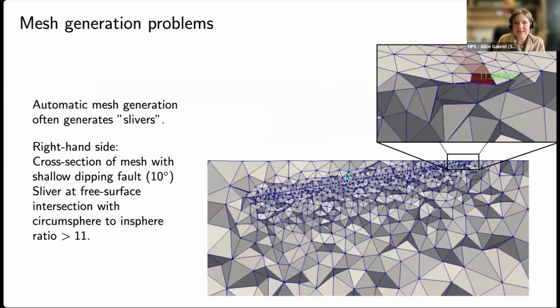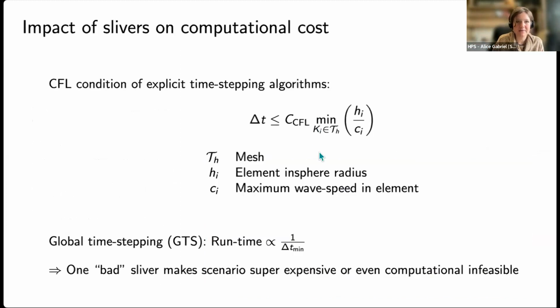So what we're doing in SeisSol is really utilizing this trick of local time stepping. That means if there's a deformed element like this, it will require a very small time step to remain stable in terms of the solution it provides. And we just let it do that to some extent, which is mitigating our meshing problems.